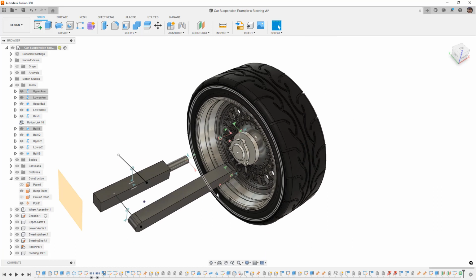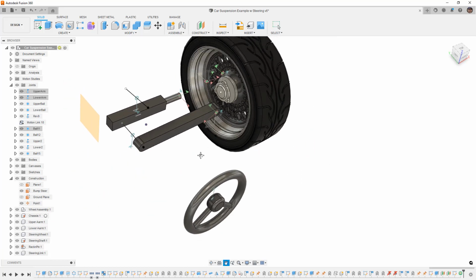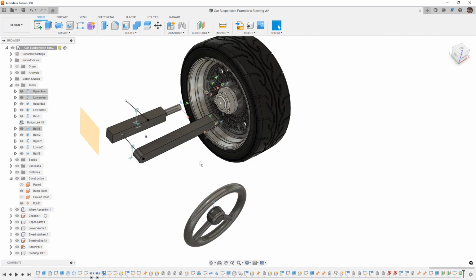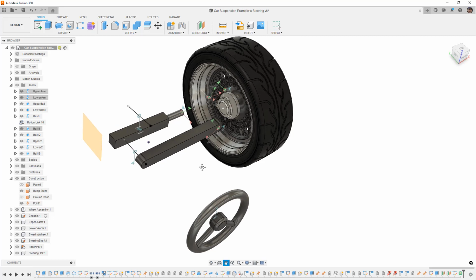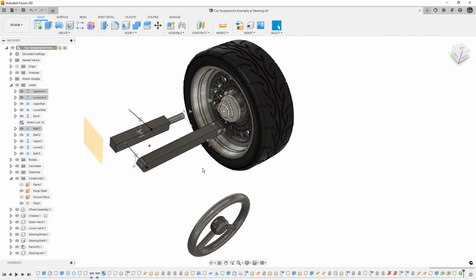All right, with all of that done, now we've got our references to measure. And again, I mentioned early on that this is not an easy process. There's no way to quickly automate this that I know of. If there is a way and you know of it, please let me know. So again, we're going to go to that steering joint, which is going to be Rev 9. We're going to lock it. Remember, locking it is only going to work when we don't capture the position. As soon as we capture or revert the position, it's going to unlock that.